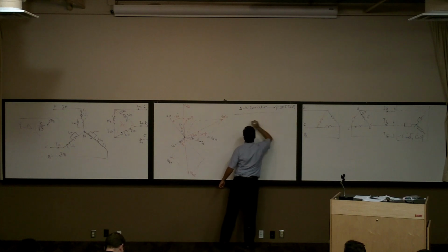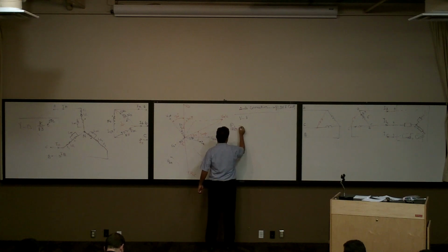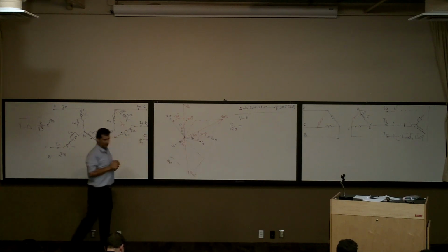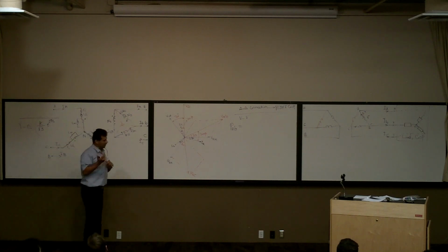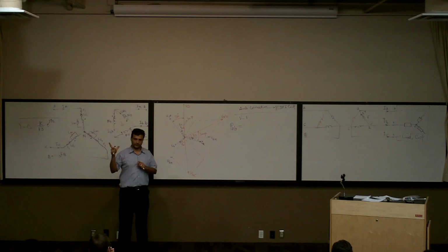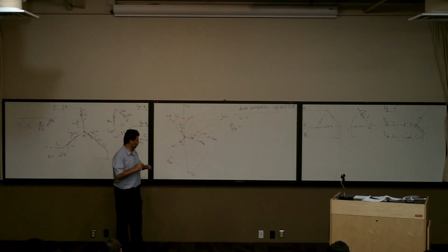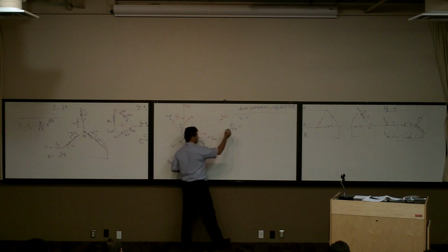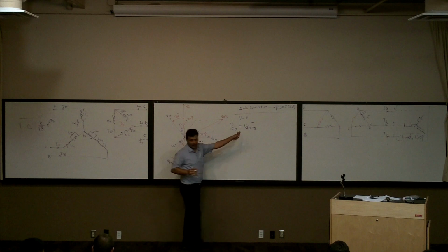So somebody tell me how much is the PAB. Look at this diagram and tell me how much is the PAB. Root 3? PAB, AB is one phase. It's going to be the voltage of AB times the current of AB times the cosine of the power factor angle. So it's going to be VAB times IA. These are scalars.